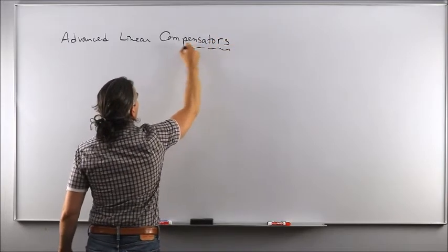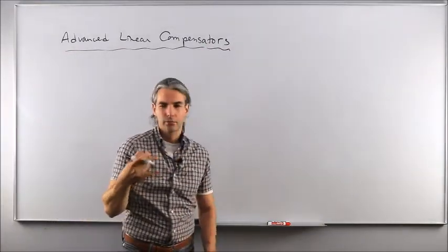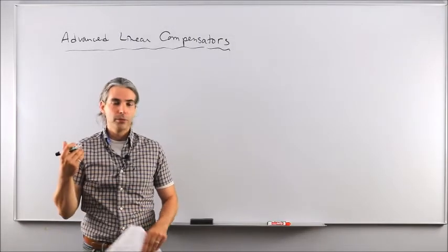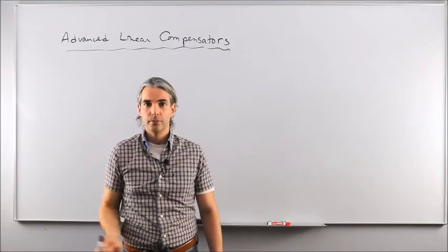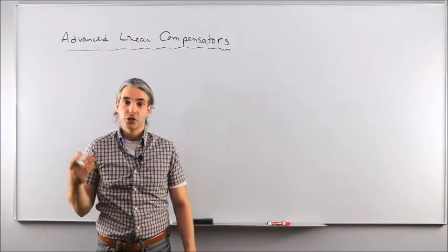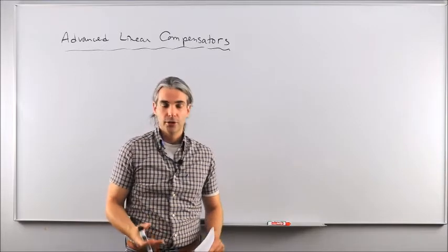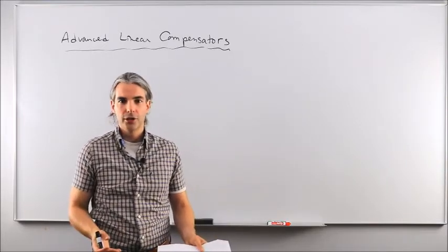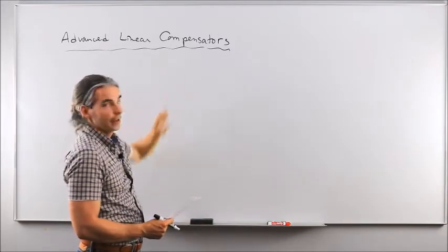Okay? Because again, the difference between a compensator and a controller, and I've talked about it at least 2 times already, is that a compensator not only will be able to bring the tracking error down to 0, but will have an additional beneficial effect, and that will be to add some filtering action to the closed loop system. So whenever you have noise, which is kind of inherent to any practical applications, using a compensator will have some benefits for you.